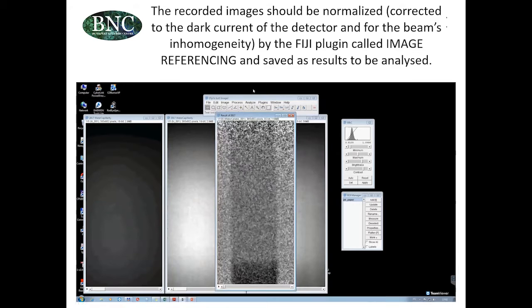The information that we want to achieve is the shadow image minus dark image over open beam image minus dark image, because that's the net intensity where the proportion is related to e to the power of minus mu times thickness, and we look for either mu, this linear attenuation coefficient, or thickness, which is the geometrical characteristic of the sample.